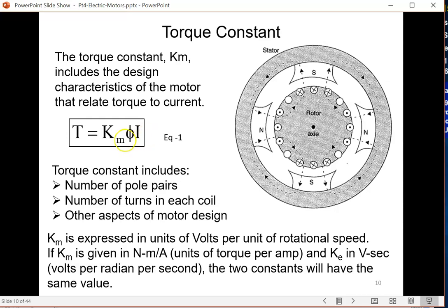And you can adjust the current in the armature winding to control the torque. Again, that's also up to a limit, because too much current will produce too much heat. Then you have a lot of losses, and the temperature in the motor can become too high.